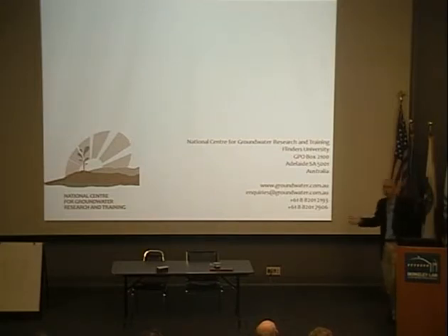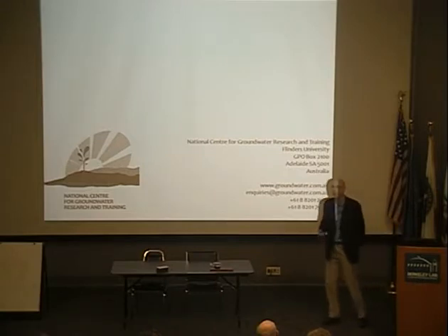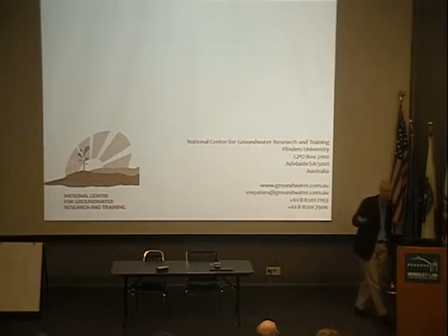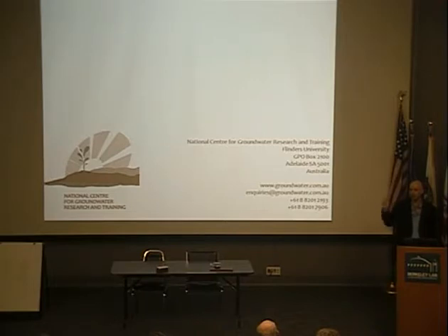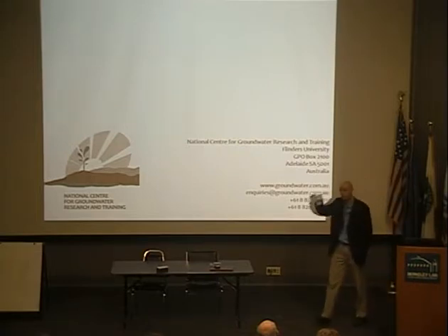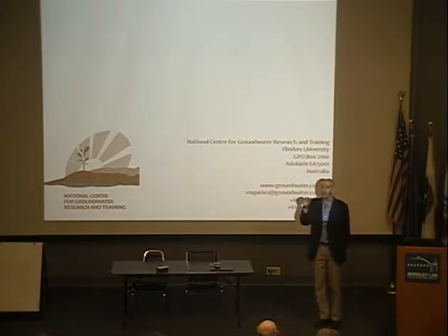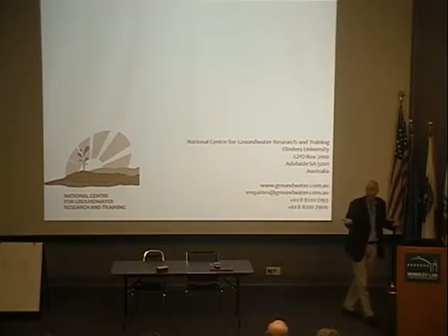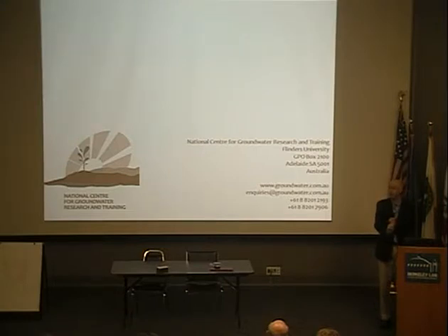We usually model these techniques as if it's just a one-way process. In the case of the water chemistry, for conservative tracers such as chloride, there is no effect. Water moving in and out of the sediments does not change the chloride concentration or electrical conductivity. There is an issue for radon. Water that moves in and out of the sediments can pick up a small amount of radon. So we specifically calculate that. We measure the production rate of radon in the hyporheic zone.